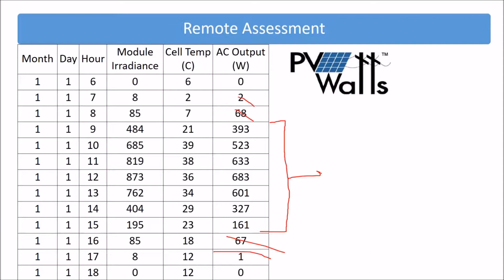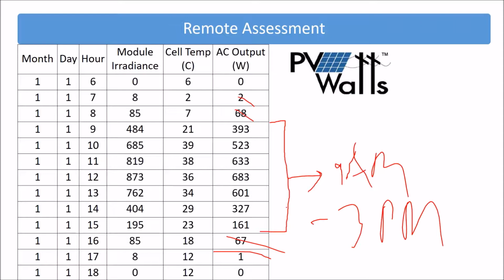And so we see that in the winter time from PV Watts, you're looking at something that's between 9 a.m. and 3 p.m. I apologize for my chicken scratch. And so you can do this by exploring, say, summer solstice and winter solstice, and you can determine what times of day your array turns on in the morning and off in the evening.